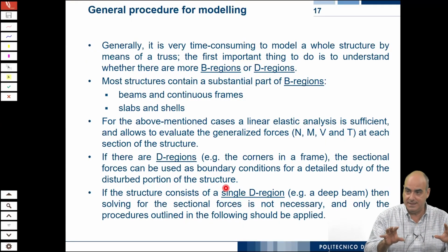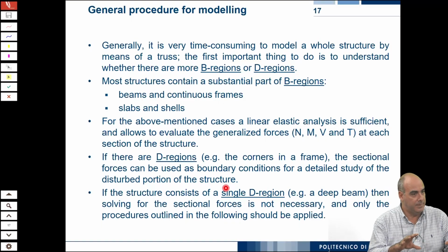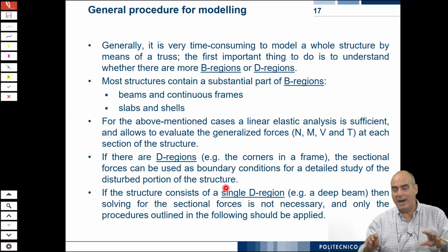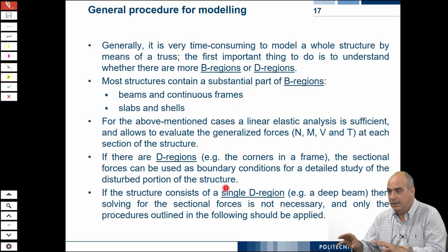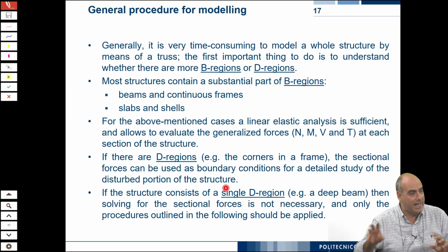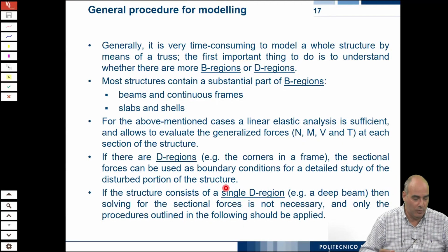So because of this, in the structural element, which are the parts that I can design applying the beam model, and which are the parts that, after having done this, I have to take care of, check and detail with a D region or strut and tie model.